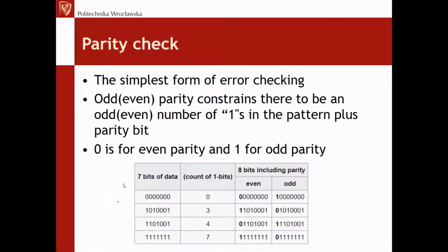First, parity checking is coding which was very popular, and still is, with ASCII numbers. The ASCII format, as you shall remember, was originally 7-bit, and to these 7 bits of data, 1 bit of parity was added. Parity means that we are adding additional information, this time 1 bit of information per 7 bits of data.